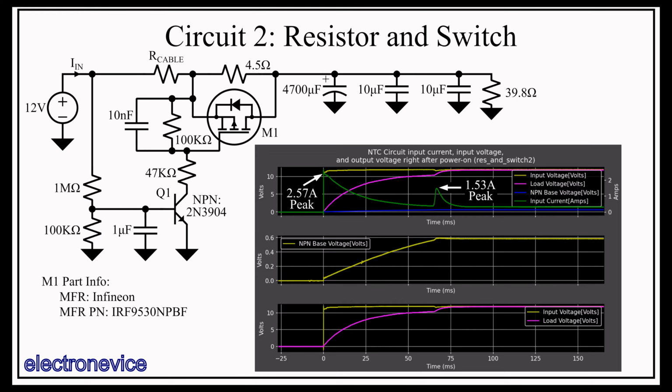This voltage difference between the input voltage and output voltage can be made to be significantly lower than the NTC case if a MOSFET with a very low drain source on resistance is chosen. And MOSFETs with drain source on resistances lower than 50 milliohms are relatively inexpensive and plentiful.